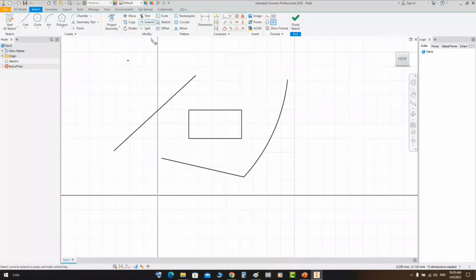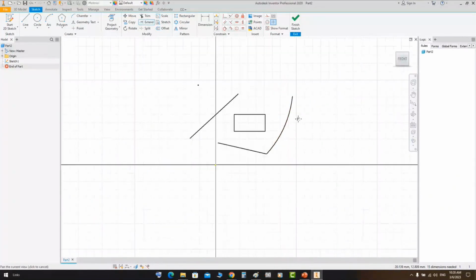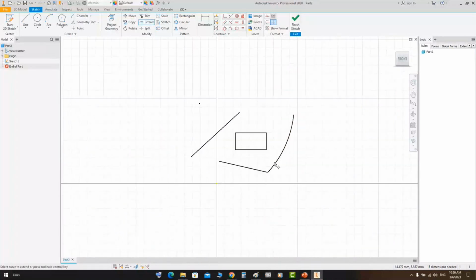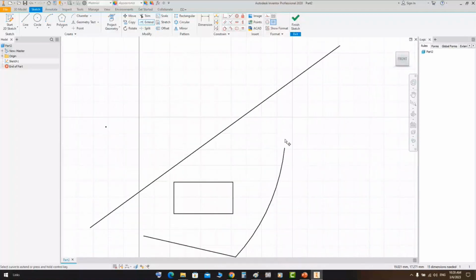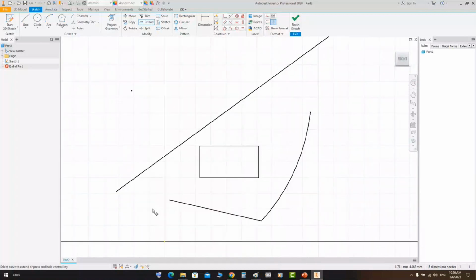Okay, extend. The extend tool will give you the ability to extend the arcs or lines. So if we extend this line like that, and you select extend, when you select this arc, for example, you will be able to extend the end of this arc up to the first line or first arc to this end. Here, if you select this one, you will get a preview.